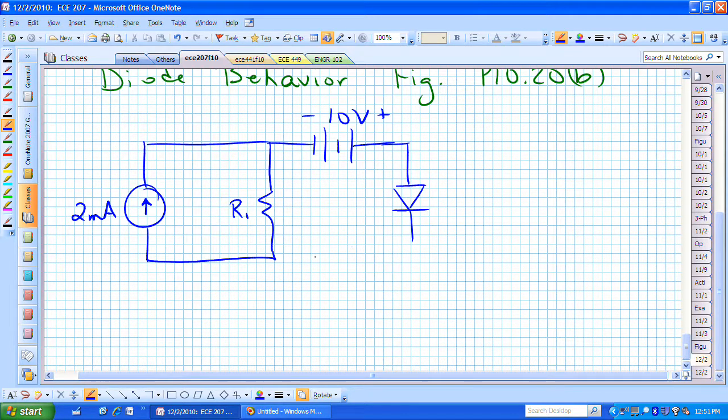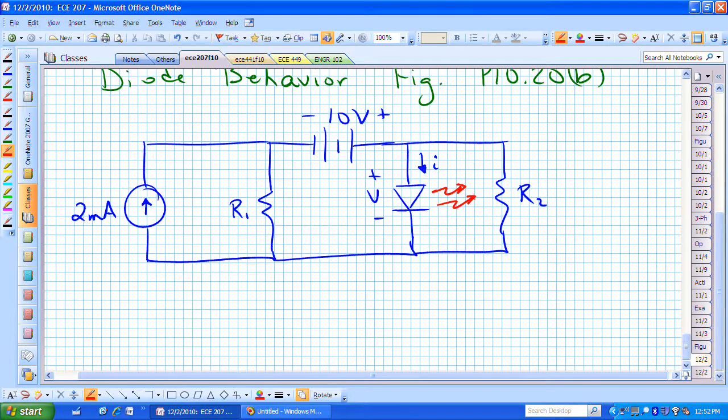Here is our light emitting diode, which they now have said, okay, here's the voltage across that. Here's our current across that diode, and here is a second resistor, R sub 2, that's in parallel with that light emitting diode. And let's just emphasize the fact that that's an LED. Maybe it's a red LED with the forward voltage that we saw that it had, which was about 1.8 volts. In this particular figure or circuit, R1 and R2 are the same, and they're 5 kiloohms.